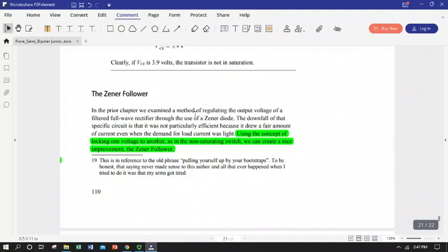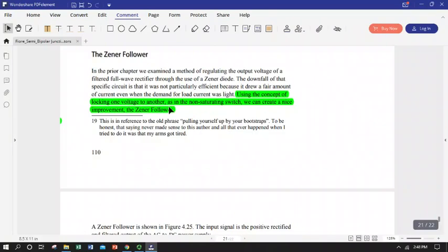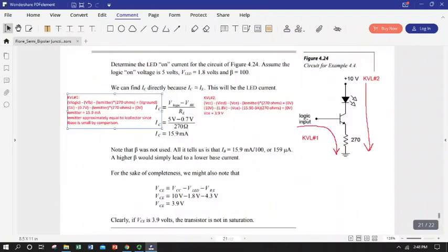Lots of ways we can apply a base voltage. So in this case, in all of our examples so far, in the case of figure 4.24, we just applied a base signal, and so we could open the transistor by applying a signal that would overcome our base emitter forward bias junction voltage, or not, in which case no current would flow through the transistor.